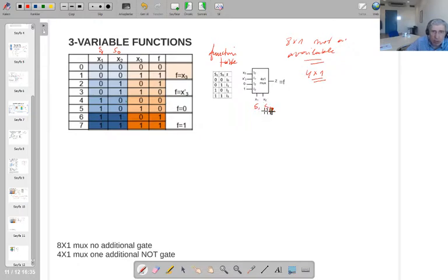When S1 and S0, in other words, x1 and x2 variables, are 0, 0, that means you are in this area. If you compare the unused independent variable with your function, in this subgroup the function value is the same as the x3 independent variable value.